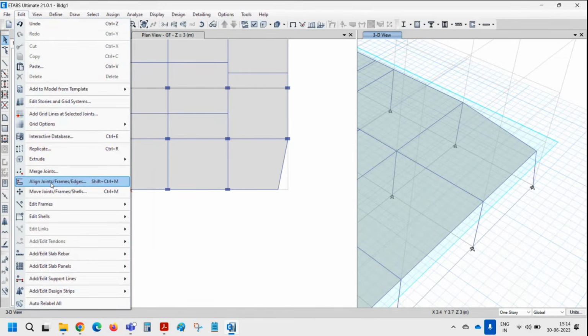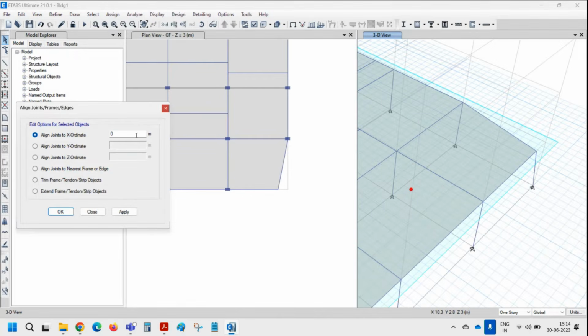And you have align command. Again, joints are powerful. So if I use any joint and move it, it will get stretched. Let's put this back in the same location, but this time instead of local delta dimension, we will be giving the exact coordinate.